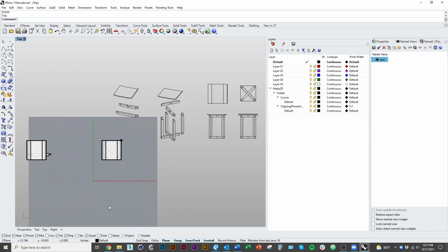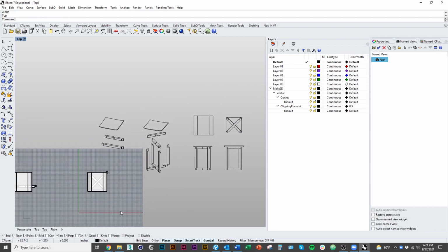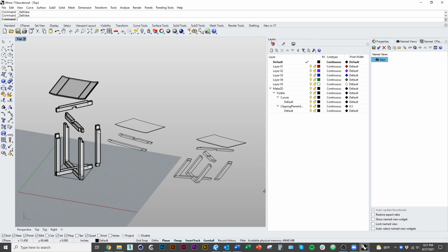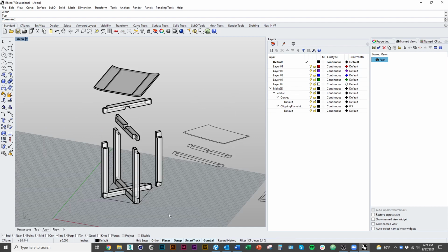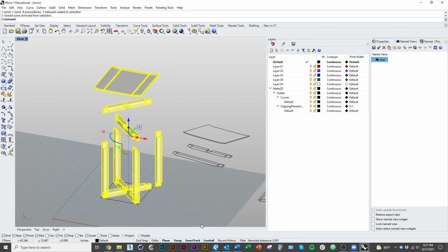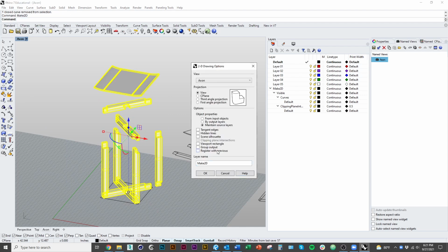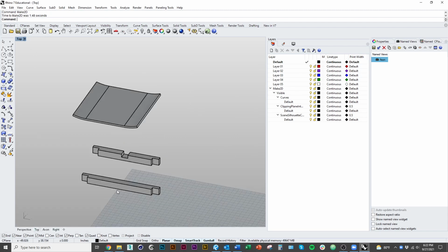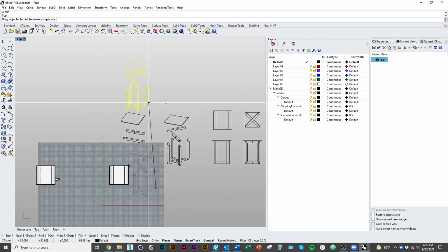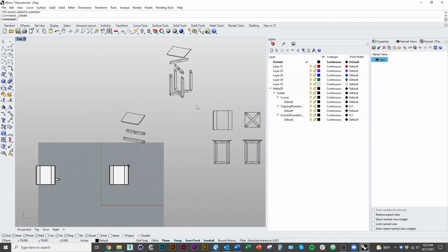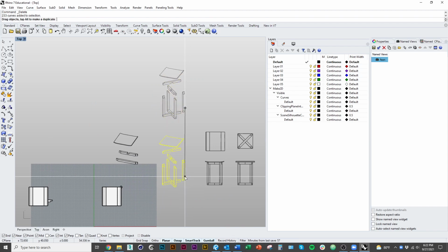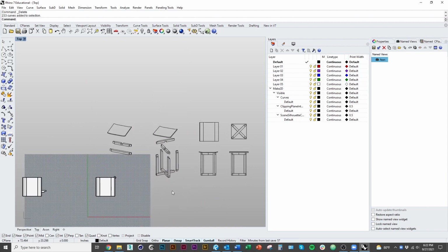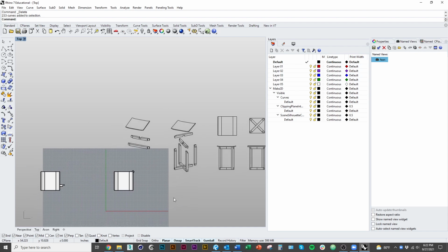All right. Oh yeah, and I forgot to mention, although I should have done this, when you do a Make2D, that's one reason we might want to go back. If I went to this one and did Make2D, this is exactly when you would want to use that option, scene silhouette, right, to get a profile line for your axon. So I will place this one. Anyway, I'll show you that in a minute, but before we get to that, I want to talk about how to draw these connection details.